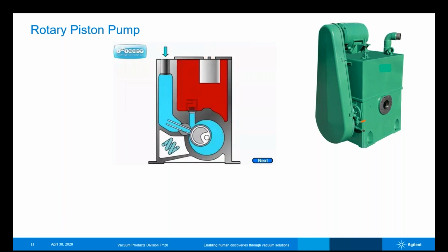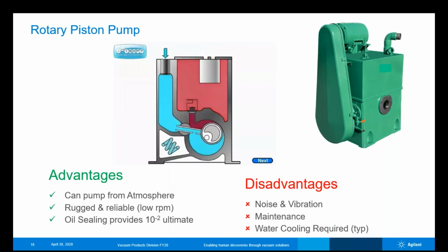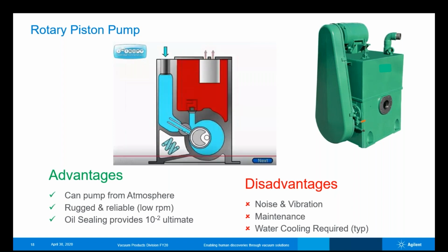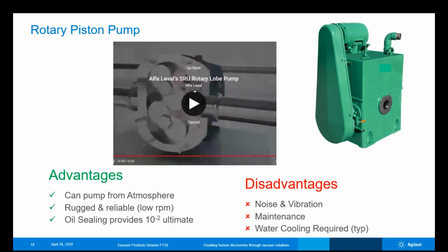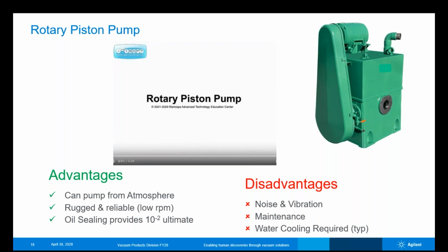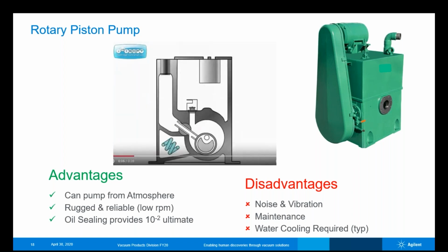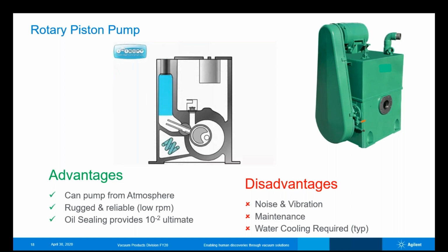Knocks against these, of course, would be it's probably the loudest thing. In fact, one of our panelists commented, when you go to almost any industrial plant, the loudest thing in that plant will be the rotary piston pump. Fair amount of vibration generated. These will almost dance across the floor if they're not bolted down adequately. Advantages is, of course, ruggedness and rebuildability. We're seeing a lot of these in applications that could be 10 or 20 years old, perhaps even older than that.